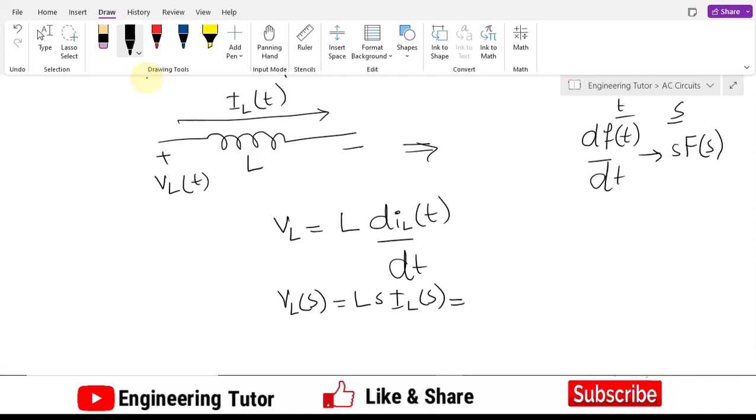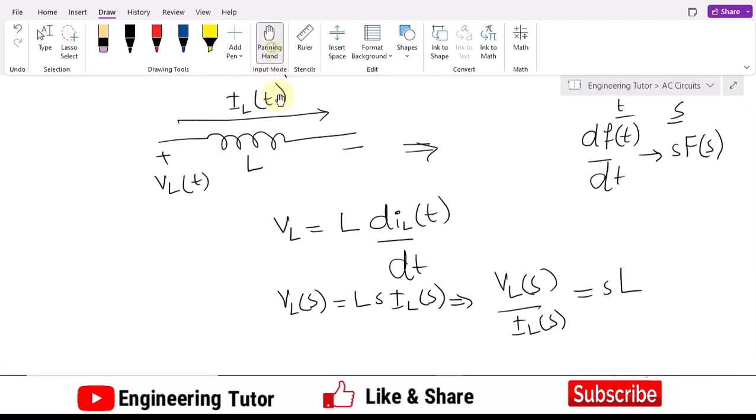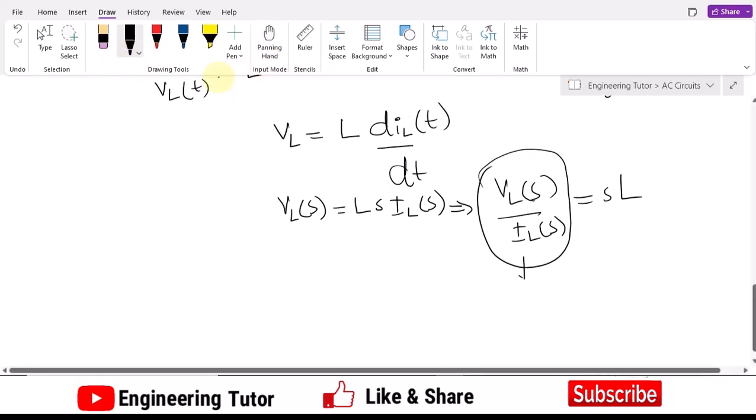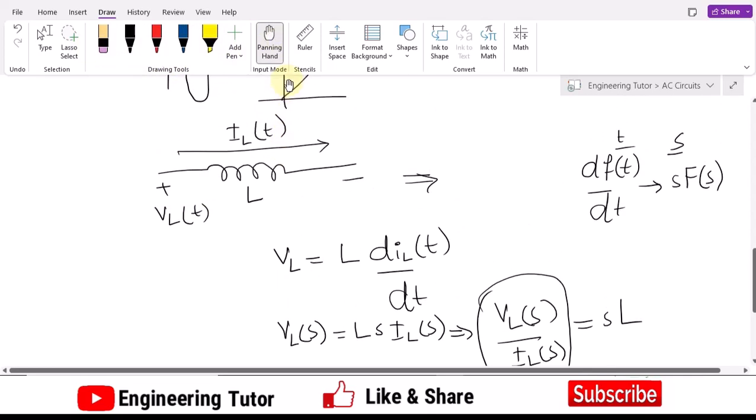Now rearranging this equation, I will get V L of s divided by I L of s, and that will be S L. We have previously seen that according to Ohm's law, this is the impedance, X L of s, and that is S L. So that is basically the value of the inductor in the S domain.